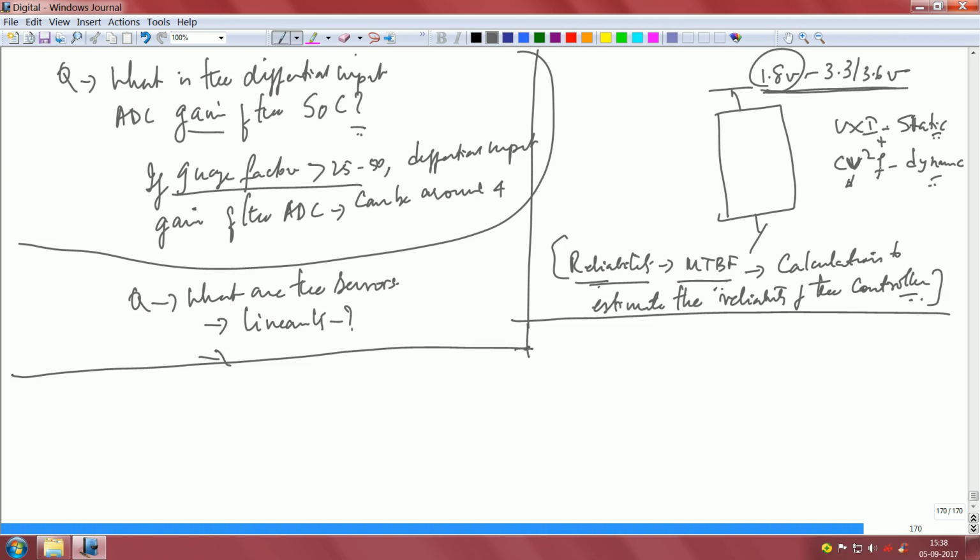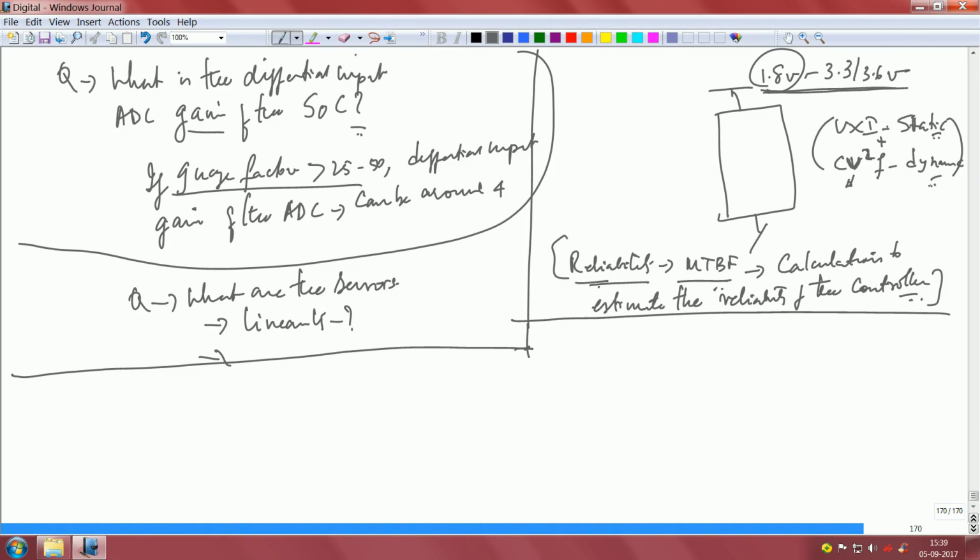Of course, F is a very important thing. The higher the frequency, the power consumption increases, as can be seen here. But if you are able to offset it by lowering V, because it changes as a square, it has a significant impact by reduction in the voltage. So this is what you have to bear in mind when you choose the controller.